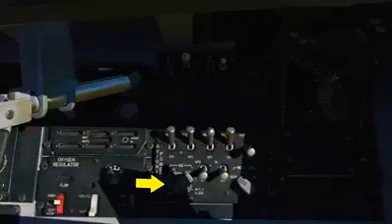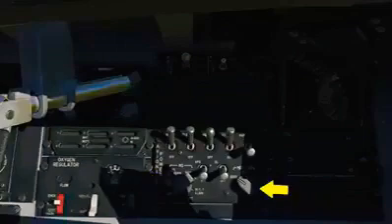And then we have the inertial navigation system knob, or INS, and this has selections for both stored and normal alignment, normal INS navigation, in-flight alignment, and an attitude alignment that allows you to fly along a set course and then have the GPS update the INS. And then last we have the multifunctional information distribution system, or MIDS, that allows you to turn the data link on and off. The seat height adjustment switch can be used to raise or lower the height of the seat for the best field of view of the HUD, and this would be used in conjunction with the HUD step option on the HUD control panel.